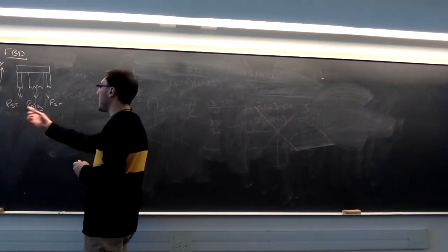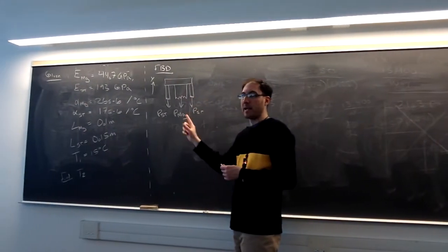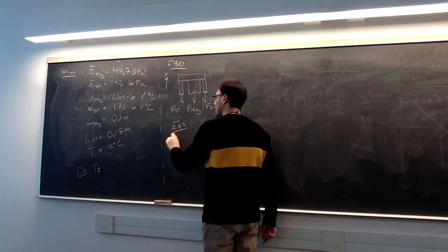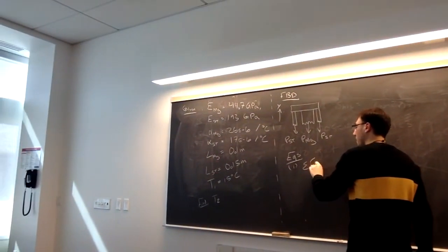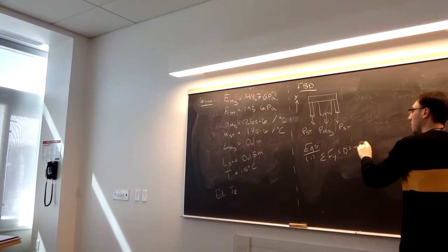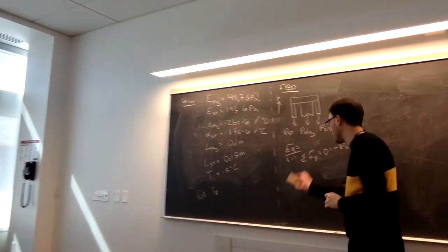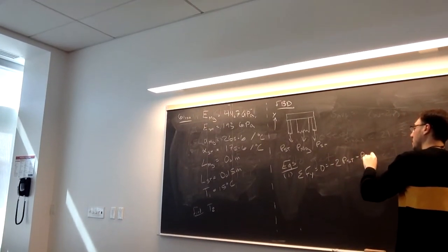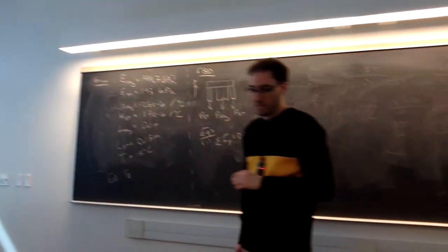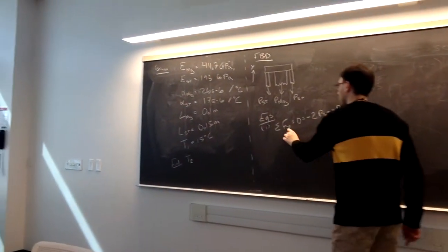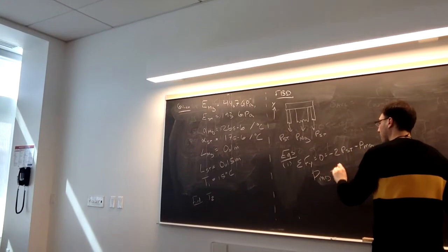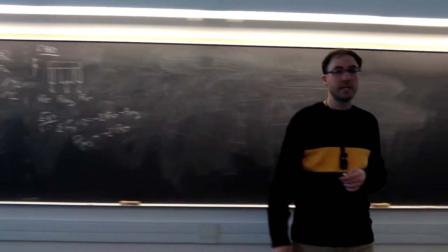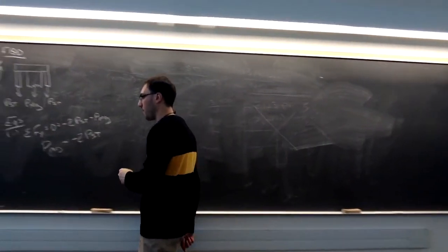So in the one free body diagram, I'm treating each steel rod independently, and I have the force in the magnesium. So this will be reflected by some forces in the y direction. Sum of forces in y will be negative 2P steel minus the force in the magnesium. And I'll rearrange it now since I know I'll need it later to make that substitution. It means that the force in the magnesium is equal to negative 2 times the force in the steel.